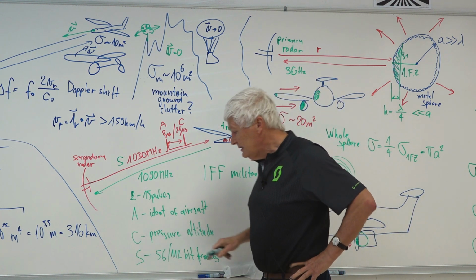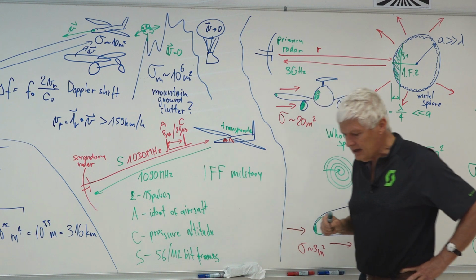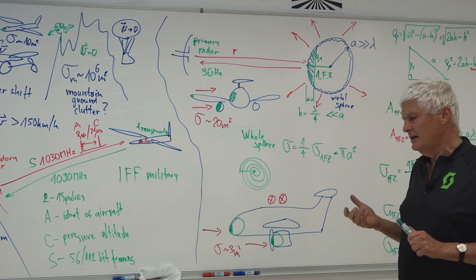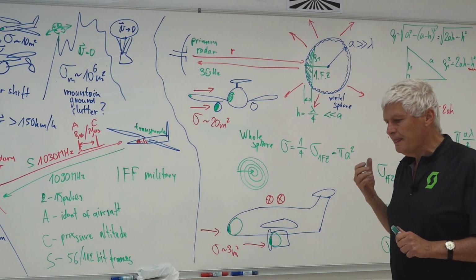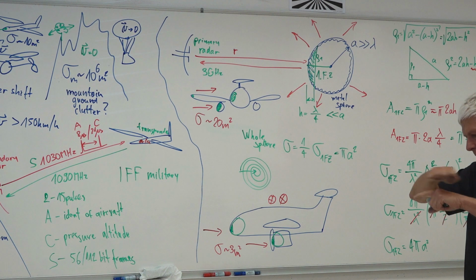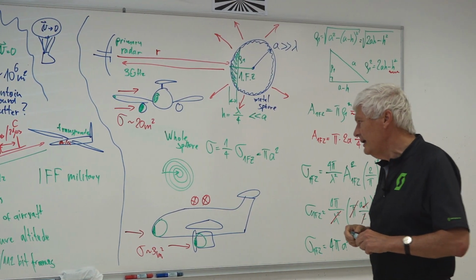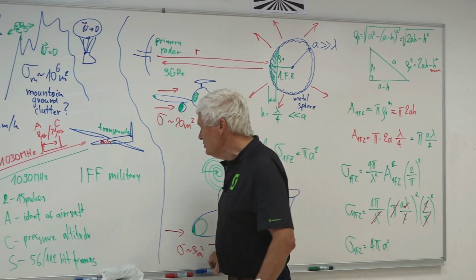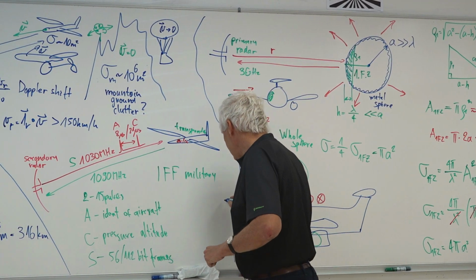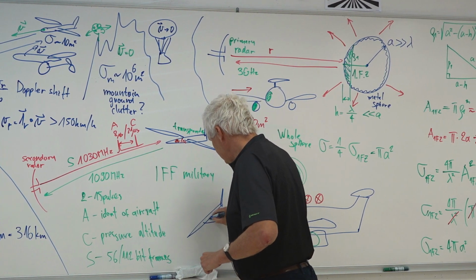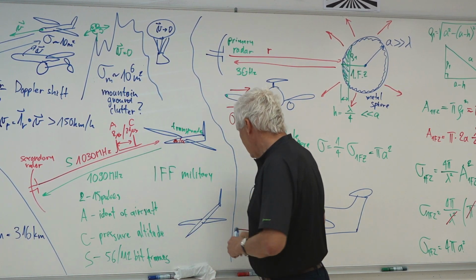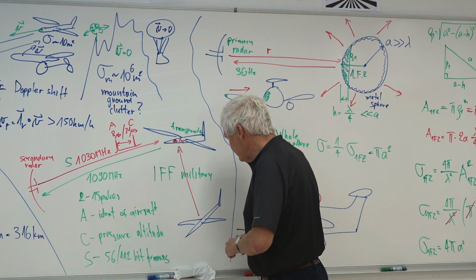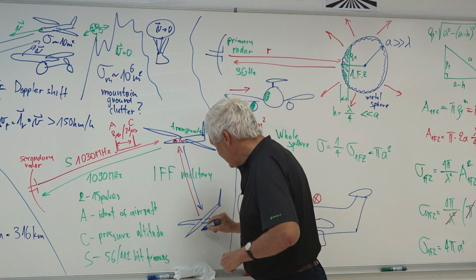And with mode C, it gets the pressure altitude of the aircraft, because the main way of collision avoidance in air traffic is to have aircraft spaced by altitude, not by horizontal position, because altitude is known to a more correct information. In the same way, you also have such a small secondary radar installed on other aircraft. Other civilian aircraft also interrogate this aircraft and get a reply back on the same pair of frequencies, and this is called TCAS.